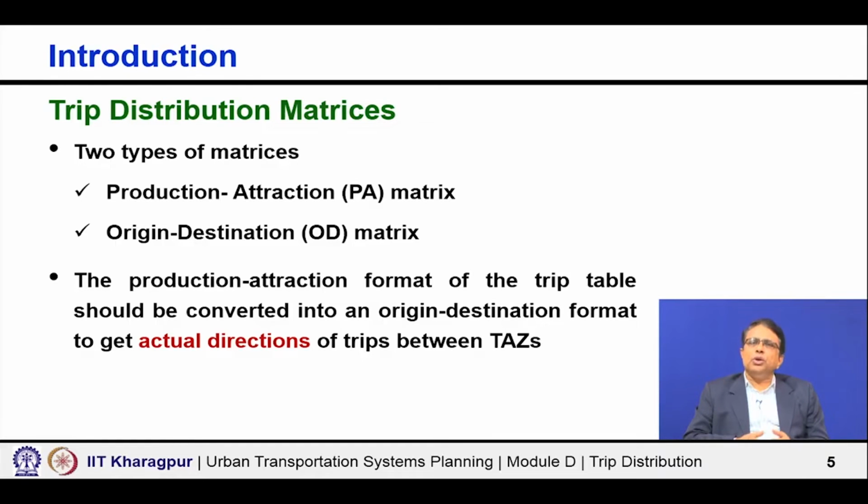Or when you are trying to see how the route choice will happen, you will see from this point to that point it is directional, right, how that travel will happen. So, the capacity will depend on whatever directional road capacity is available, compared to the directional demand, because in the other direction, which is not the peak direction, the problem may not be that severe. So, the problem will always be in a particular direction where more travel is happening.